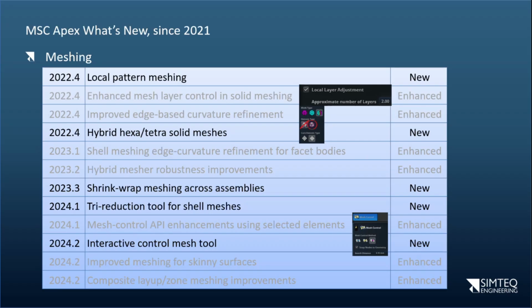But it's actually extremely useful for anyone doing acoustic simulations, where you then literally take, it's literally like shrink wrap that you fill or stretch over the whole model, and it creates a mesh around that, essentially filling any small gaps or ignoring small features, and just creating a nice closed mesh around the whole assembly. But as I say, not as useful for structural analysis, more used in the acoustic simulation side of things. Some people even use this for CFD preparations.